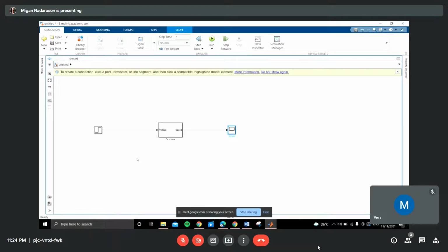For the desired response of 1, we did get 0.1. This is due to the percentage error that is happening in the system. For the percentage error, the main keys are the desired response and the actual response. And the formula is desired response minus actual response over desired response times 100, and we would get the percentage error.